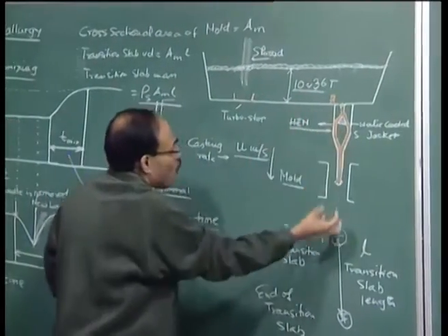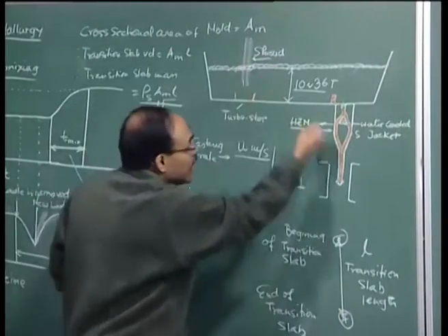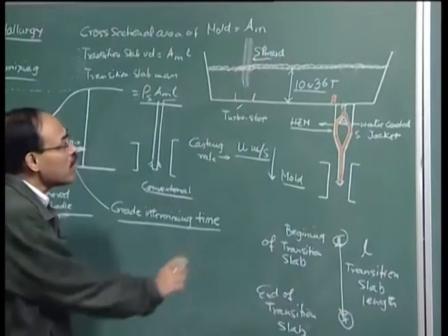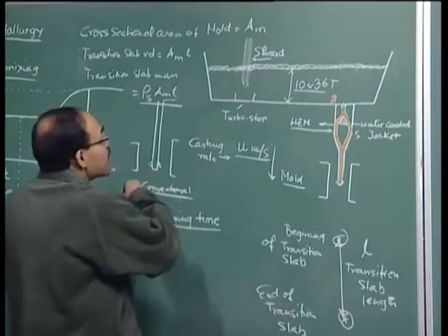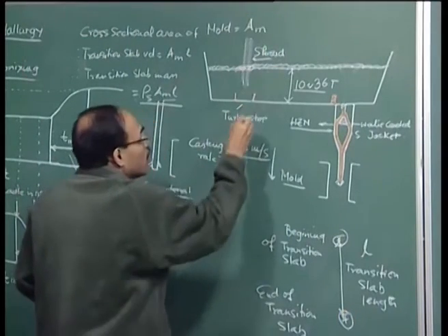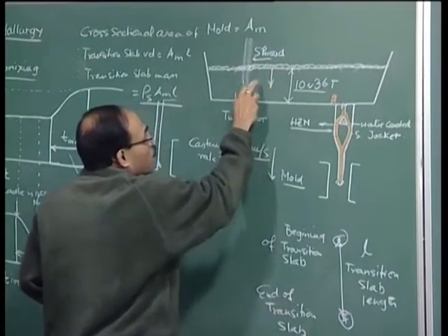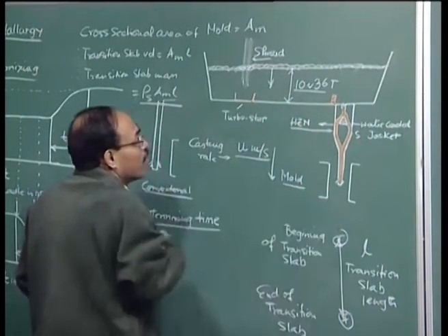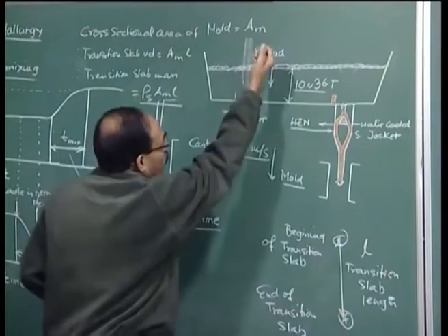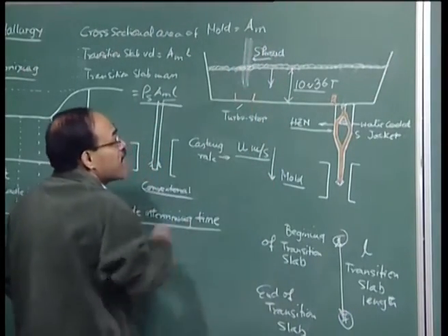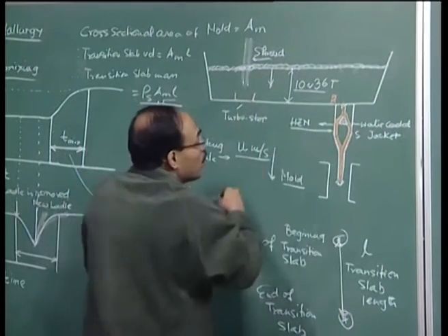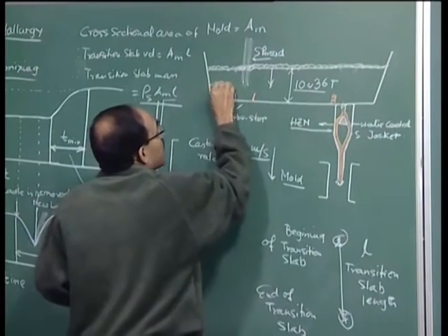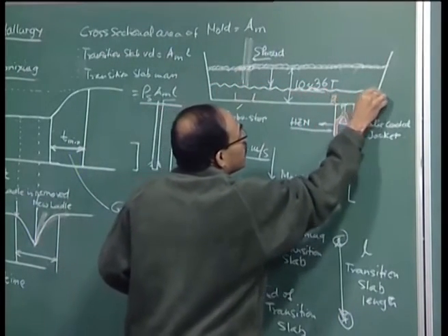Now the casting goes on, and the objective is to salvage the entire amount of steel in the form of solidified product. But now, as I have mentioned already, as the depth of the liquid falls down, the surface descends. Why does the surface descend? Because nothing is coming in, the only thing is material being drawn from the tundish. So, therefore, the bath depth really decreases, and as the material drops down, immediately above the nozzle there is a formation. So, imagine that the material now has this level. Okay. So, the slag is here.